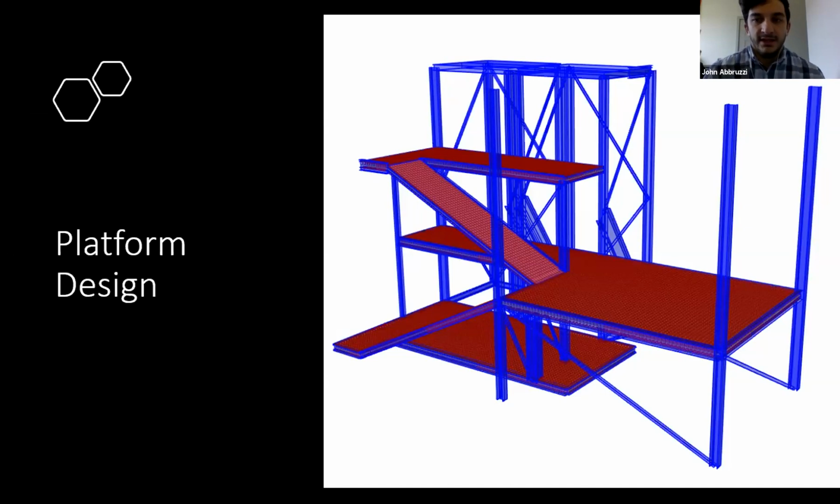From there, we began applying the dead and live loads to the structure. All standard dead and live loads were taken from ASCE 7-16. An extra 15 PSF live load was applied to the structure to account for any utilities. There's also a 60 PSF contingency live load applied to the structure. This load will account for any future desired changes to utilities by the client. After applying the loads, analysis was then run on the structures.